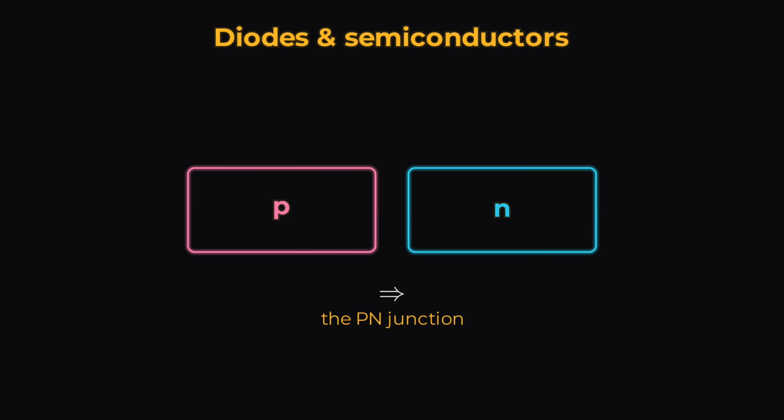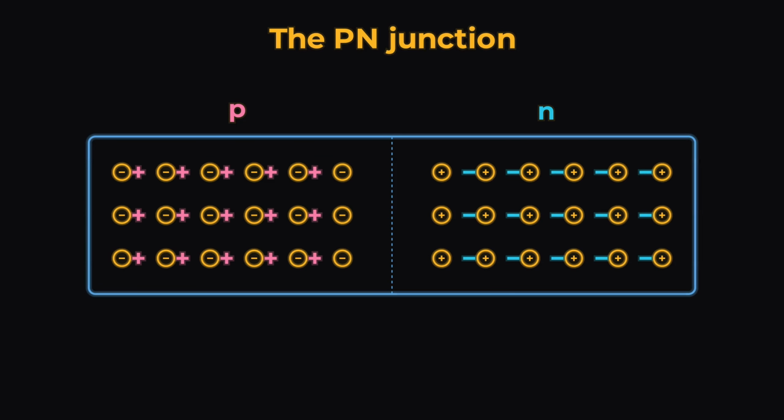So what happens when p-type and n-type silicon meet? This leads directly to the junction. A p-n junction forms where p-type and n-type material meet in one crystal. The two sides start with very different carrier concentrations. That difference sets everything in motion. Two transport mechanisms act at the junction. Diffusion moves majority carriers down their concentration gradient, from high concentration to low. Drift moves carriers under the force of an electric field.